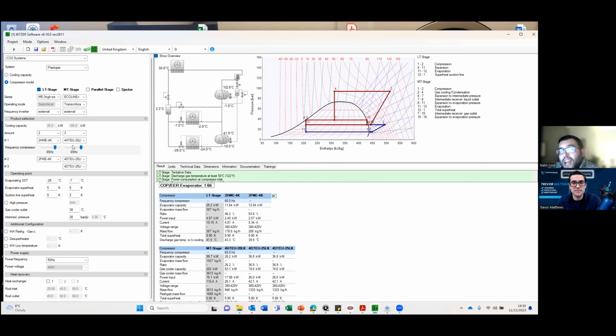In terms of maximum inverter frequency? Well, just in the sizing of the compressors themselves. Well, I would prefer to size at 60 because then you get a wider control range for that lead compressor. And therefore you will have less gaps in your output when you're staging. So for me, I would prefer to see it at 60, not 50.